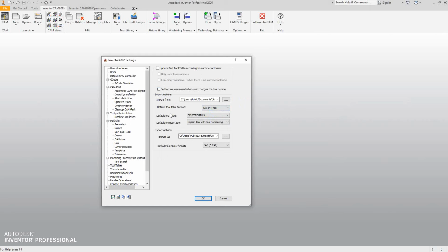When I open up the Browse button, I can choose which global library I want to look at. All the libraries that come with InventorCAM are listed here, so you can select whichever one you want. If you've created your own tool libraries, that will be covered in another intro video. When you create your own libraries, they will also be on this list. So if you tend to use the same tools over and over again, and you don't want to have to load them individually, you can go to Browse for global libraries, have the library you've created yourself automatically selected, and automatically import all the tools.